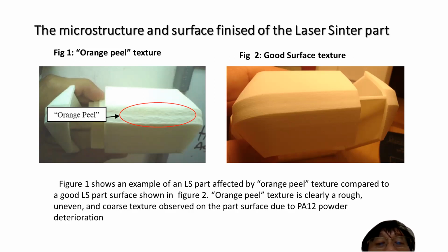The related research reviewed here by Gornet studied how the mechanical and thermal properties of laser sintering parts made from Duraform, which is the trade name of PA12 powder produced by 3D Systems, were affected by the number of times the powder was used in the Sinterstation 2000. Gornet used the plastometer, a commonly used tool in the injection molding industry, adjusted to measure the flowability of the used Duraform powder.